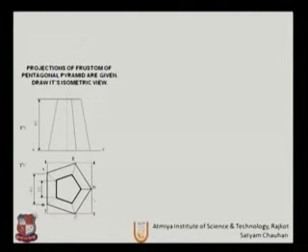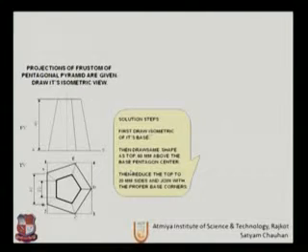What are the maximum dimensions we require? We will produce it in isometric. So first draw the base, and then draw the shape with the top 60 mm above, the height is 60 mm, and the base pentagon at the center. Then reduce the top to a 20 mm side and join with the proper base corners. These will be the steps.